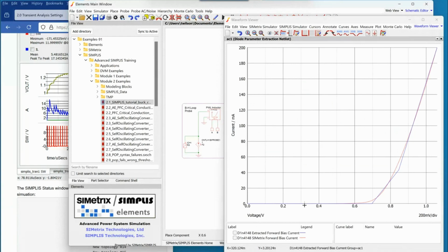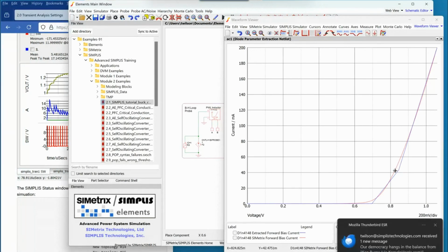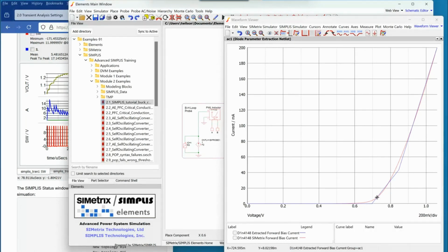What it's going to do is we specified 200 milliamps, and it's going to go down to about half of that and draw a straight line there. And so in this neighborhood, about 20% is where you're going to often see more error. And similarly, when we're getting down more in the neighborhoods of 1%, you'll see some more error.